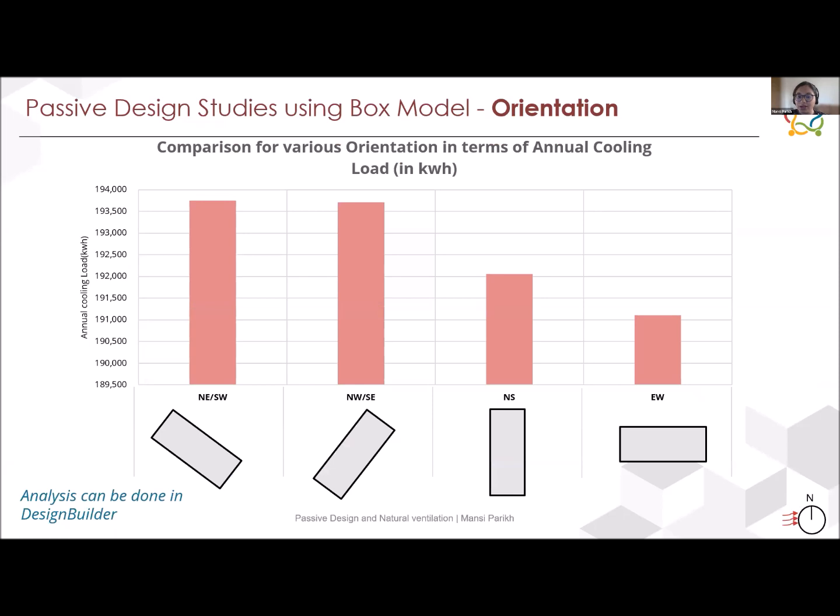The next step for us was, once we have passive design strategies which were selected, post-climate data analysis, which we discussed in session 1, we started looking into studies for orientation, shading, window to wall area ratio, and conducted the impact analysis of these principles. These studies help to explain to client and architects the impact of these strategies in the design process.